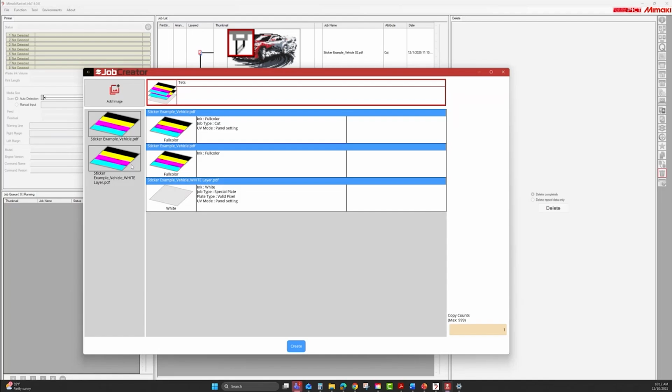The cut edit file will identify multiple cut lines, but you'll need to identify what tool is associated with each cut line. Same with jig settings. If you have a jig already loaded on your computer, on your RasterLink, and you want to use that for a file created with Job Creator, that will work, but you need to specify what jig it is.